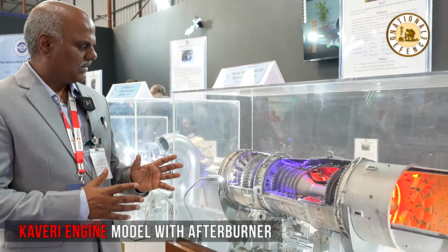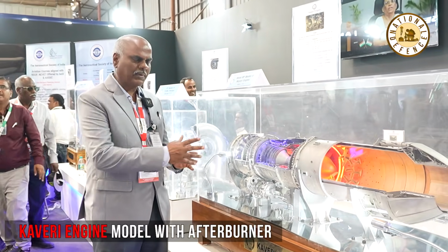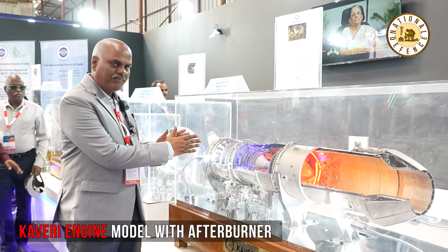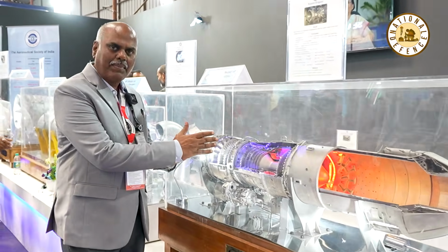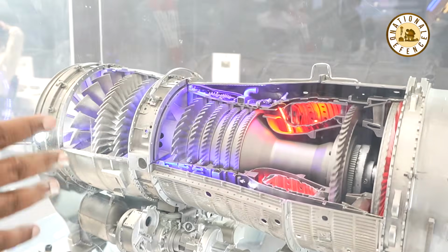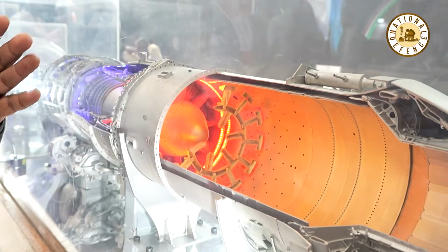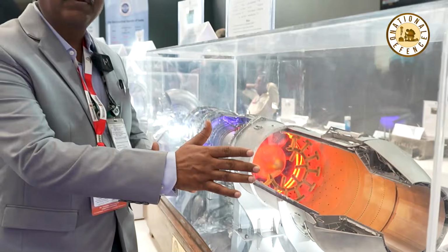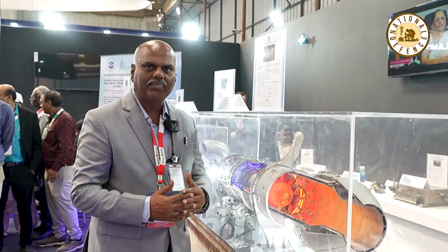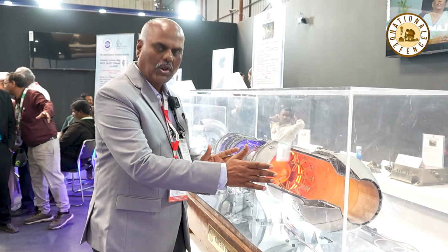This is the Kaveri engine model. This is a twin spool low bypass ratio afterburner engine. This is the fan, the high pressure compressor, combustion chamber, turbine. So this will be generating the gases. After the gases, there will be a converging and diverging nozzle. It will be expanding, so it will be producing the thrust from the nozzle.